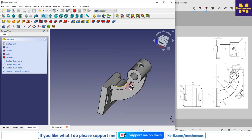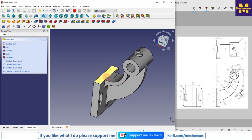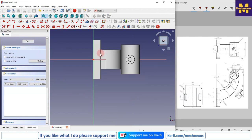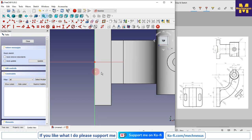So we have made this material removal, but here is also a cut. So I will select this face and this surface, create a sketch, and I will switch to the isometric view and then top view. So this is a 30 by 5. So I will create a rectangle,